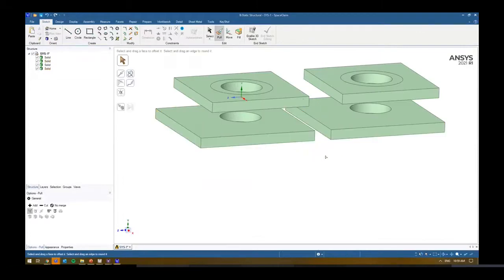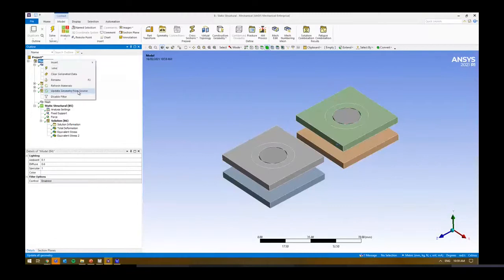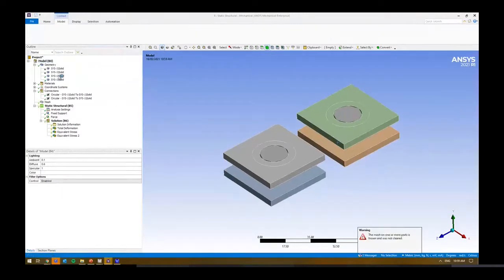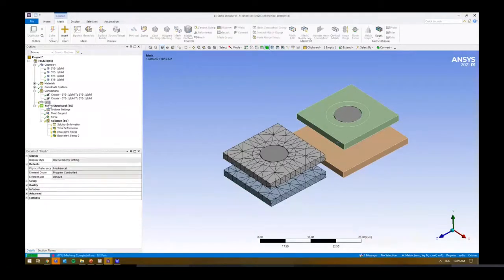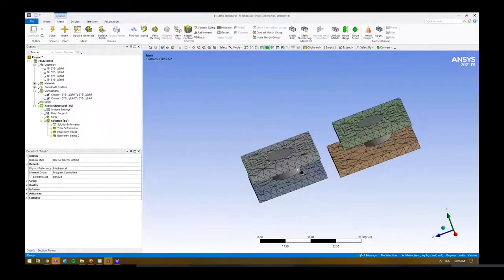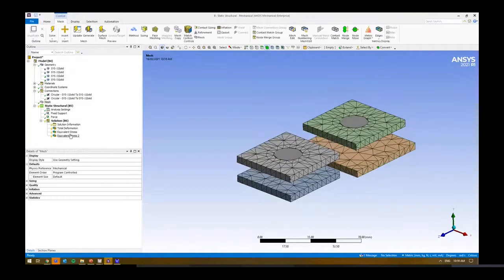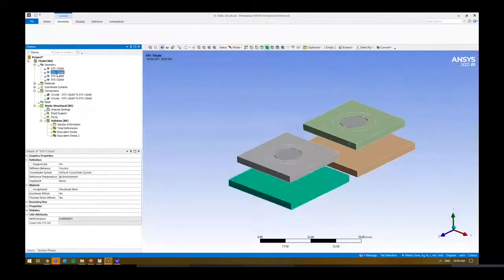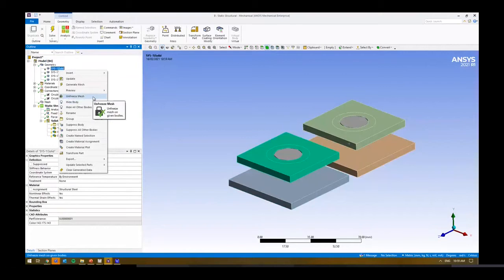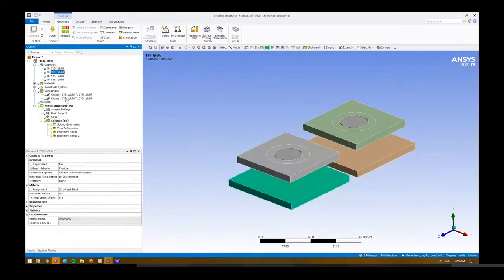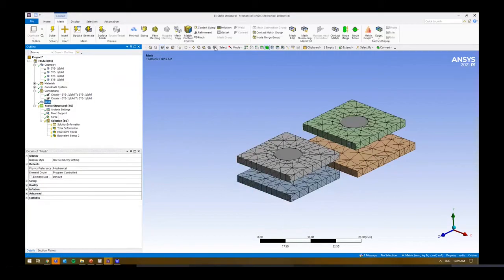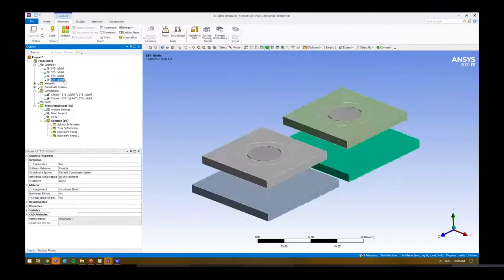I'm testing this on the fly, so let's hope it doesn't break or I haven't forgotten to do something. What we should see happen, oh no, we've got both of these two things that changed, right? So, okay, even though the body's changed, the mesh stays exactly the same. You can see the mesh changes on the right as well, right? So you can see that you can use this, so it freezes the actual mesh given on that component, right? So that's if you wanted to fix whatever meshing constraint or geometry you've created and just compare between the two of them. That's one of the ways that you can do it. If that helps, Stefan.